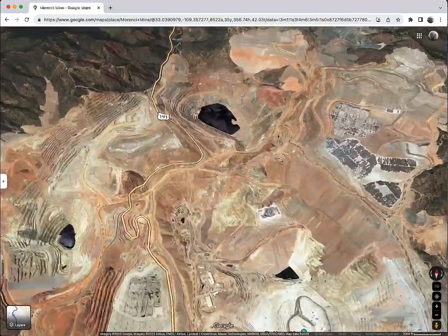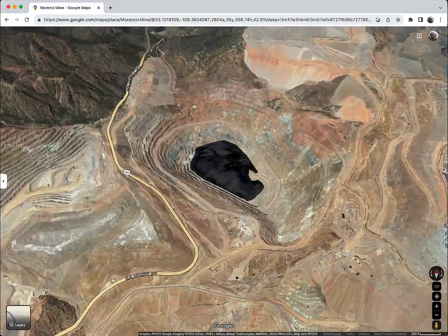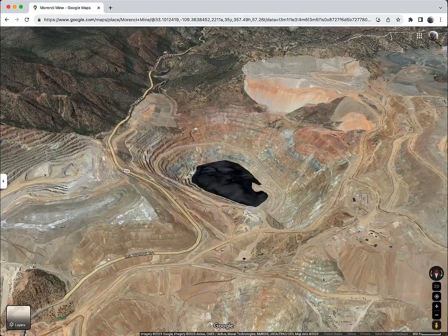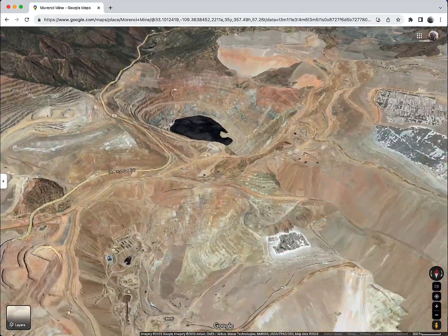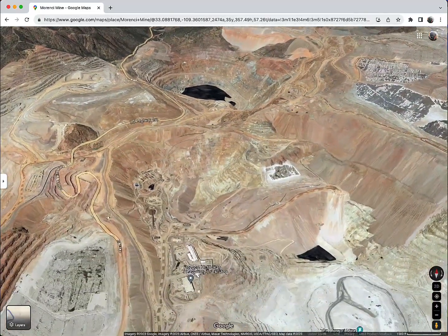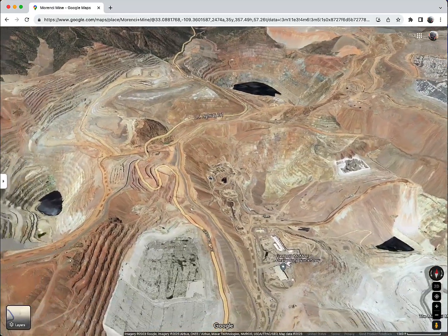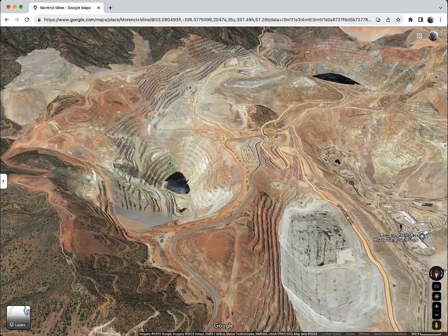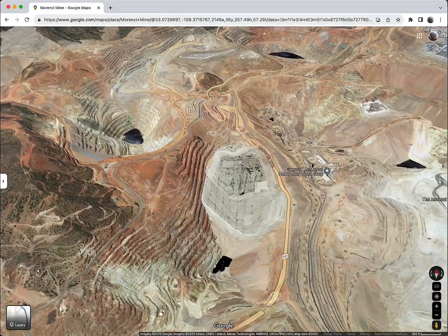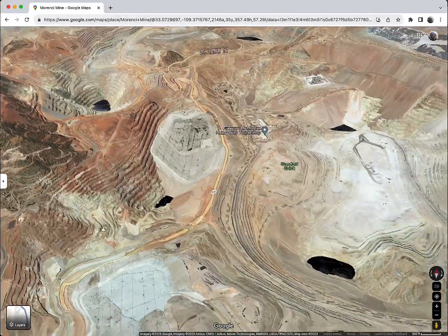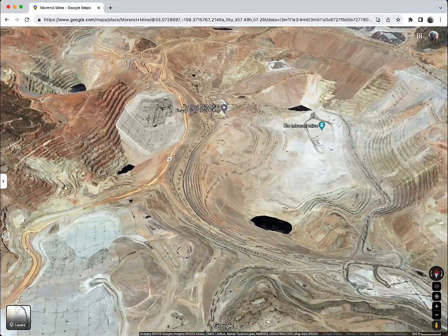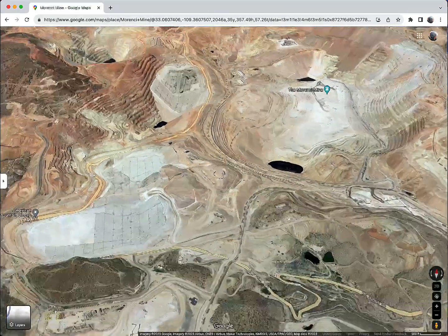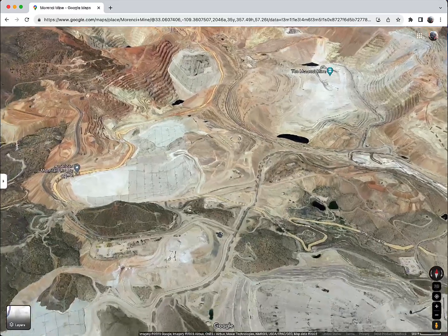Mining is designed to take place on 50-foot wide benches, with haul ramps that are 120 feet wide with a steep 10% grade. As of December 2022, mine operations included over 1,700 employees and contractors, involved with drilling, blasting, loading, hauling, and auxiliary support, utilizing 13 electric rope shovels, 6 front-end loaders, and 146 267-ton capacity haul trucks, all supported by a fleet of track dozers, wheel loaders, motor graders, backhoes, and water trucks.